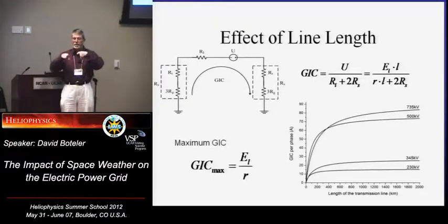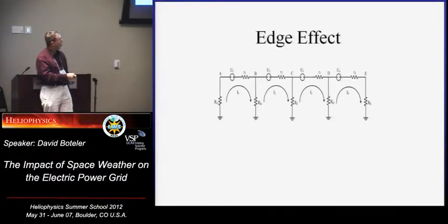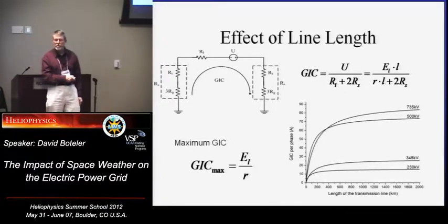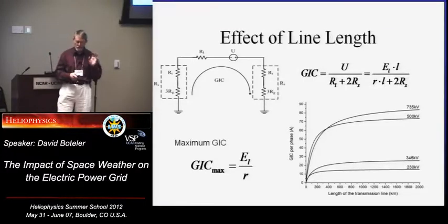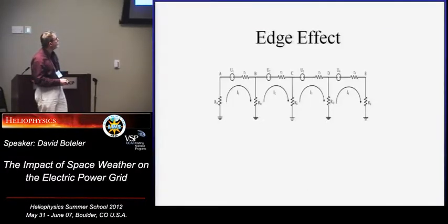If you have four conductors on spacing, it gives you the same effect as if you've got a very large conductor. So as you go to higher voltages, these are typically single conductors, these are typically double, and then by the time you get up to these voltages, these are four-conductor bundles, and sometimes even going up to six-conductor bundles. And so you've got more conductors there, so it's a lower resistance path, and so you get larger GIC flowing in those circuits.